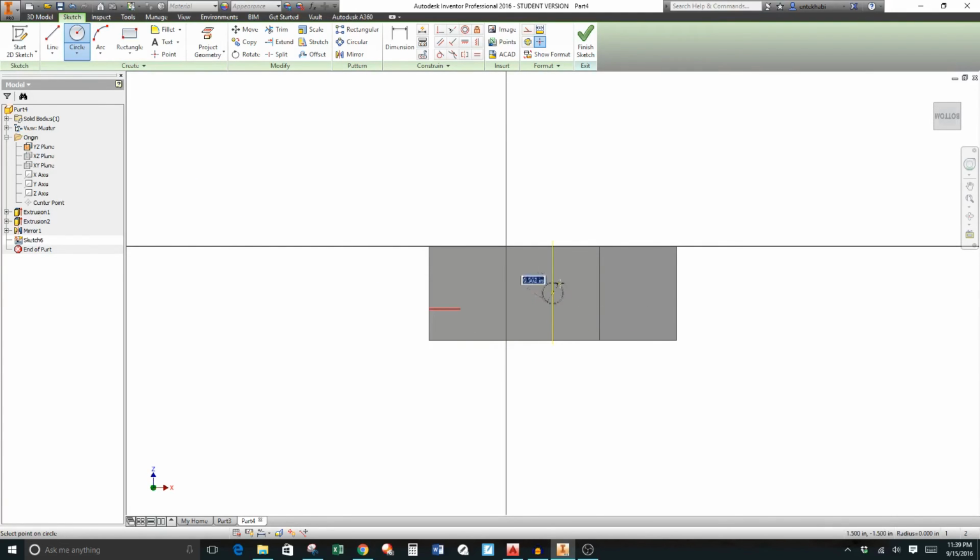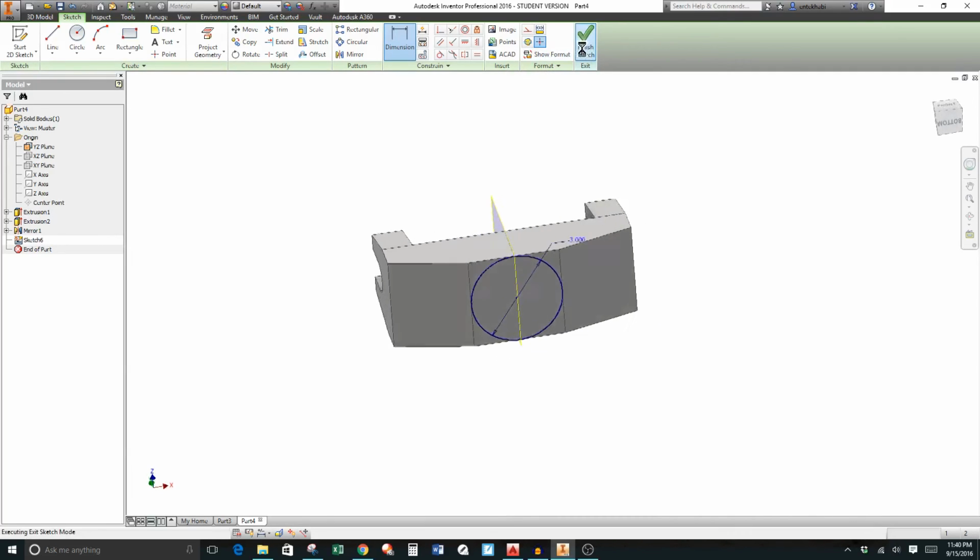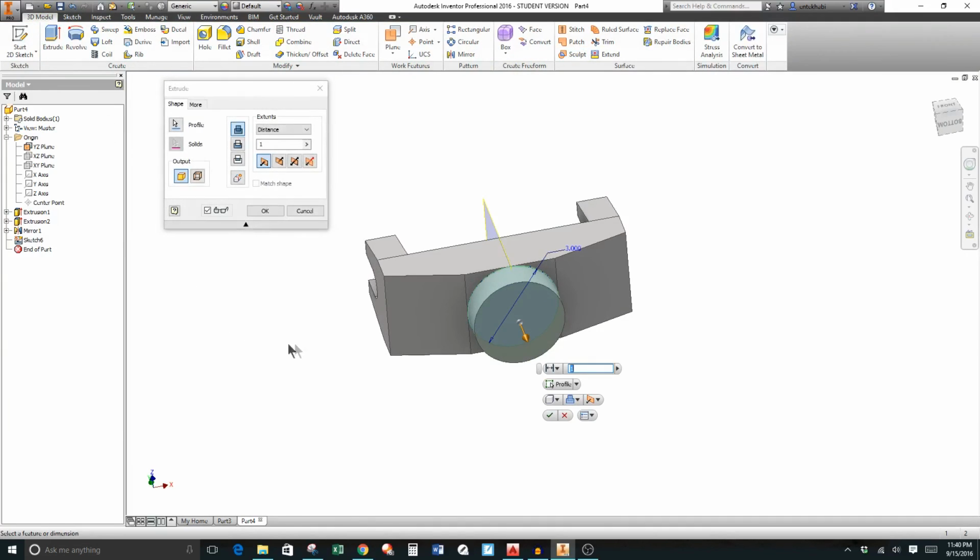and then select the bottom piece as a new work plane. We begin with the circle and snap to the origin. That's the advantage of having the extrude in both directions, it gives us the origin in the center. This makes it easier for constraining the object quicker and faster, and that's fully constrained.